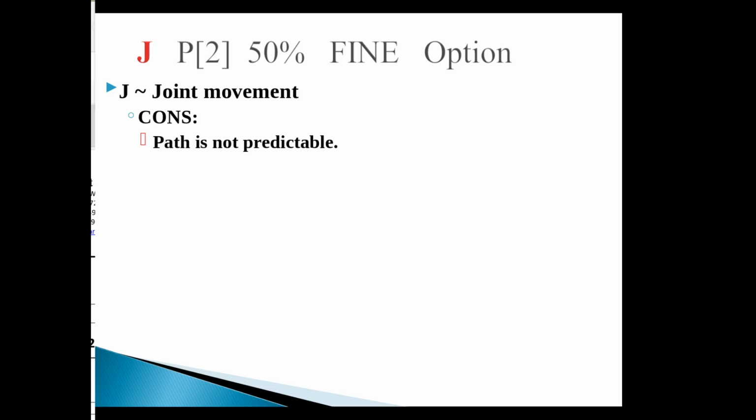All right, so when we're testing it in teach mode, the robot may move along and move around an object or something and not touch that object. However, when you put it in auto mode and then maybe you test it again and it's still not hitting some object that's there, but when you run it up to full speed, it may actually run into that object because it's not following the same path.